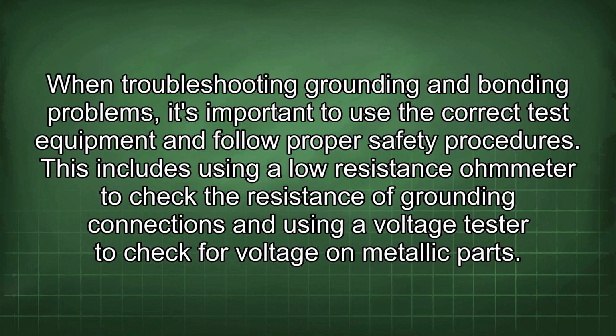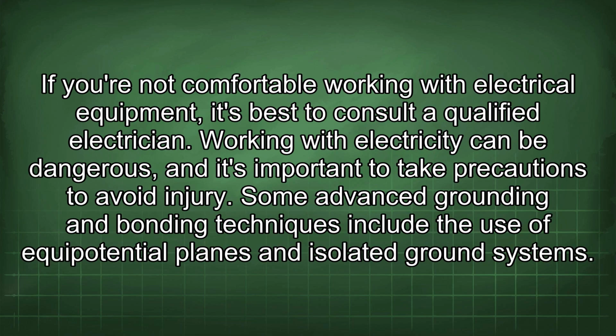This includes using a low resistance ohmmeter to check the resistance of grounding connections and using a voltage tester to check for voltage on metallic parts. If you're not comfortable working with electrical equipment, it's best to consult a qualified electrician. Working with electricity can be dangerous, and it's important to take precautions to avoid injury.